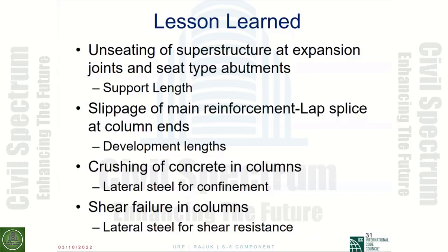So that's what you want to really calculate: what is the force that will come from the plastic hinging if you have a plastic hinge at the top and the bottom of the column, and you have to amplify that to be able to design it to take the shear inside the column so that it wouldn't be the weak link.